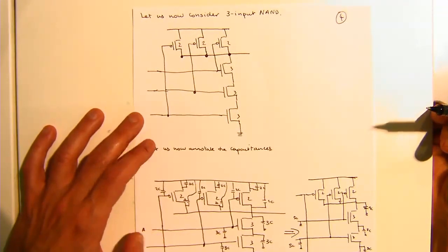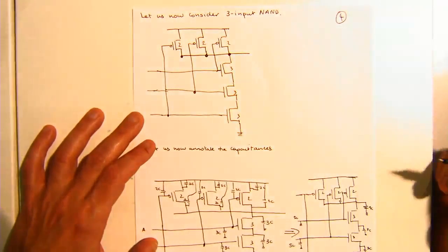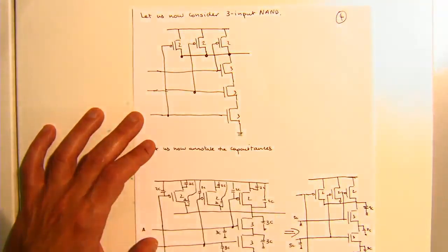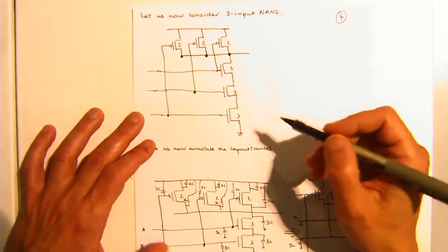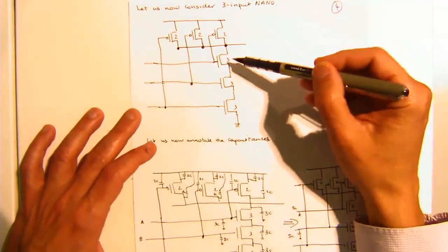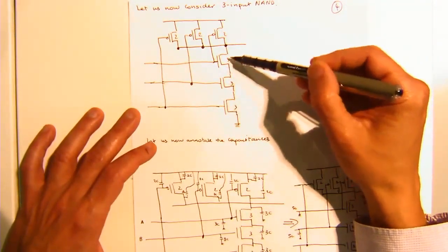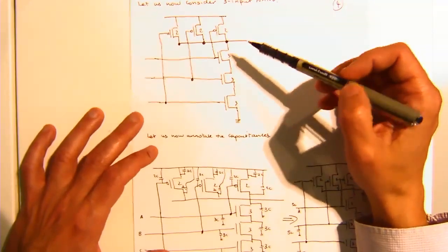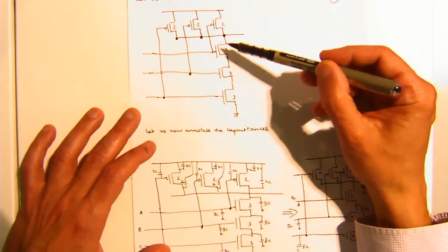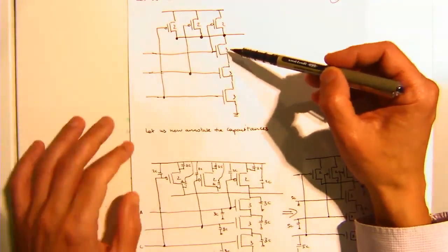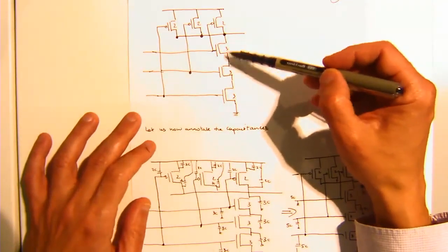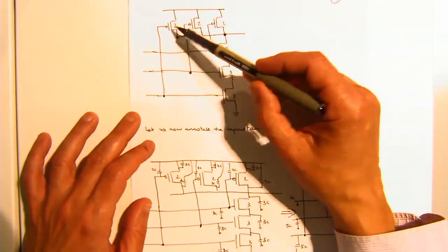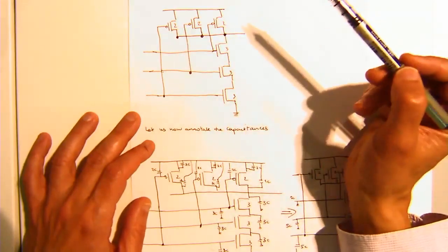All right. And what we've got is three PMOS transistors, and we've also got these 3 NMOS devices in series. In this particular case, and for good reason, I've chosen the NMOS devices to be 3 units large and the PMOS devices to be 2 units large.